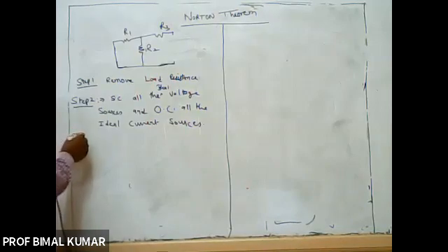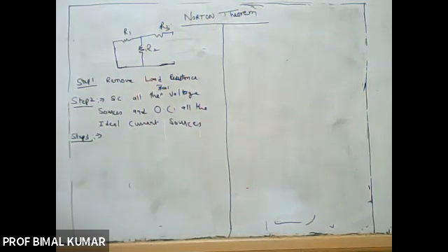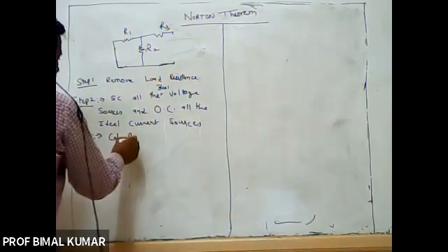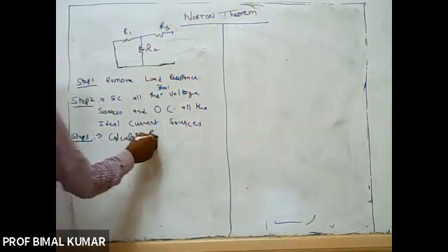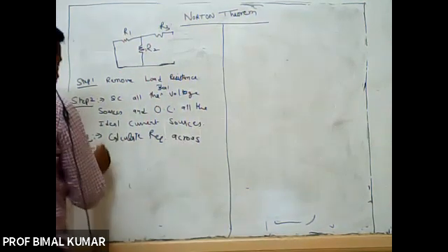Step 3, calculate R equivalent across the load resistance terminal.